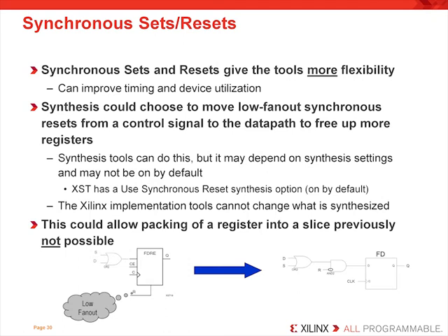In this example, as you can see at the bottom of the slide, a low fan-out reset has been coded into the design's HDL. After it is synthesized, XST has chosen to move it to a LUT input. This could allow the component to be packed with other similar logic into the same slice, that is, logic that uses the same control signals, and this would improve device utilization. Either way, it is added flexibility given to the implementation tools to meet your timing and as a recommended design practice. So keep in mind that this could be the biggest reason to code for a synchronous reset.